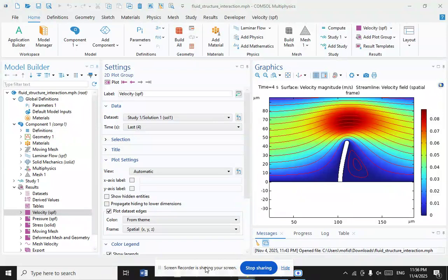This is especially difficult if the mass of the moving structure is small in comparison to the mass of fluid which is displaced by the structural movement. In addition, the treatment of the mesh introduces other classifications of fluid structure interaction analysis. For example, one can classify them as the conforming mesh methods and the non-conforming mesh methods. Other classifications can be mesh-based methods and meshless methods.